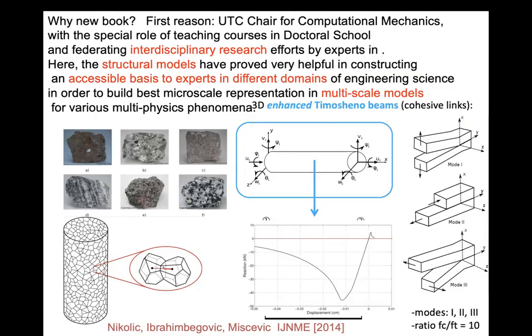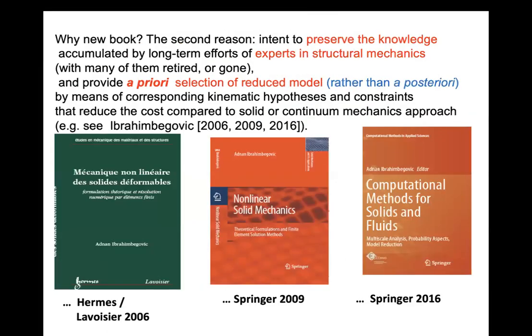It's really like dislocation, and the rotation is not only important, but you know, axial and shear deformation is giving me the mode of fracture, which is mode 1, 2, and 3. And then rotation I can even neglect, but that gives you the tool how to model this. And we were quite successful modeling the fracture of complex composite materials like the cement-based composite.